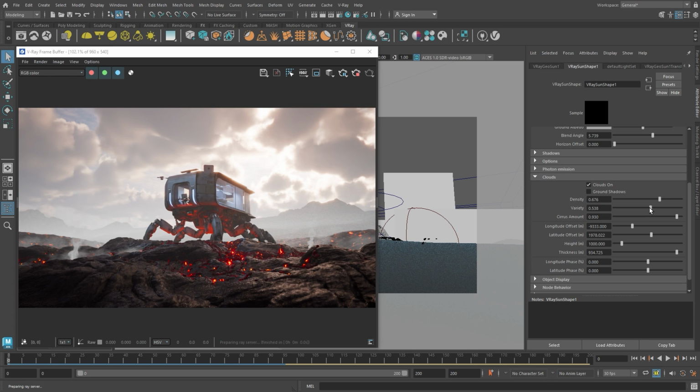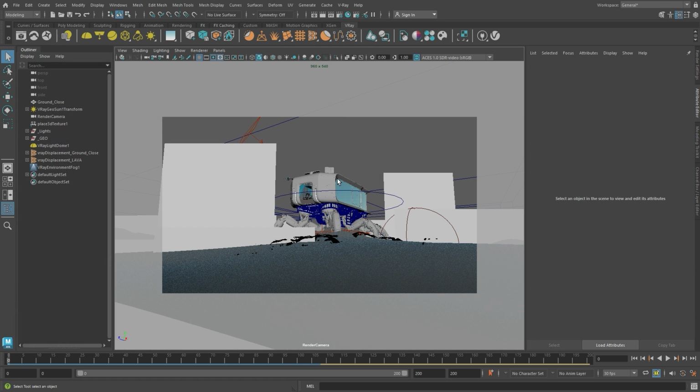Before we start rendering our final shots, we should always make sure that every material is optimized so render times will be minimized. To do that, we use the V-Ray Profiler. This handy tool gives you a detailed analysis of how much time V-Ray is spending on rendering different material properties and volumetrics. Let me demonstrate how you can easily check if your scene is properly optimized.